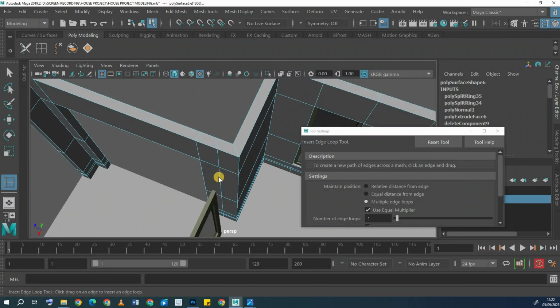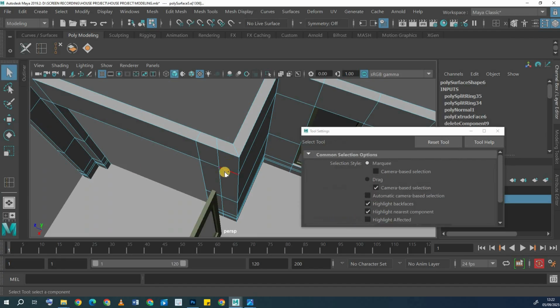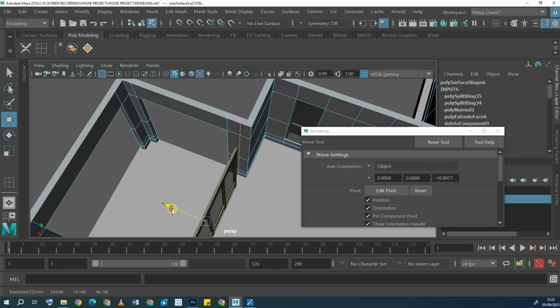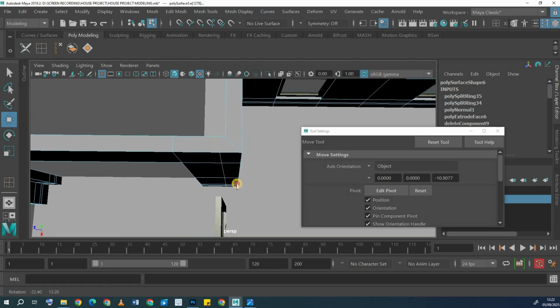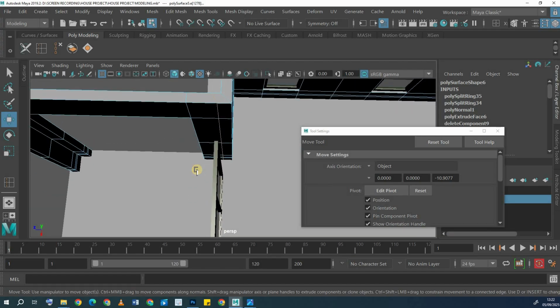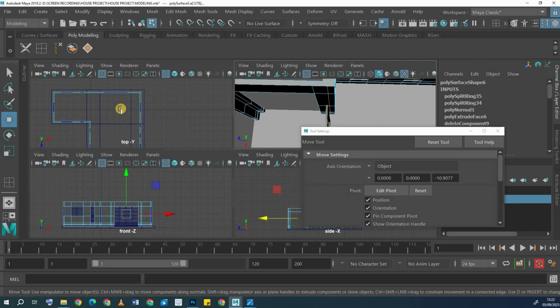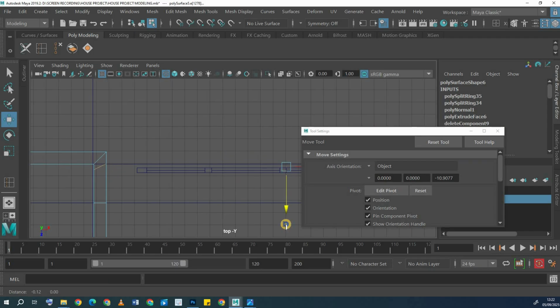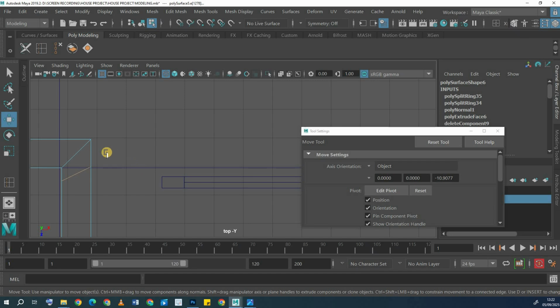Double click them both. So we should find the easiest way to do something. They're both selected. I want to extend them so they look like these walls. It's a bit close. Let me see the top. Yep, it should be touching this line here.